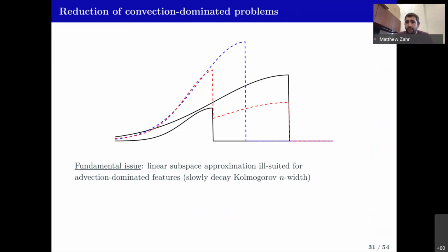We want to deform the domain. I've been talking about it as a mesh, but it's really an underlying domain deformation to align the shock in the snapshots with the discontinuity. Now, within the DG setting, all of our elements are in some sense created equal, and we piece them together to cover the full mesh. But in this setting, each one of our snapshots is covering the full mesh, and we want them to work together.